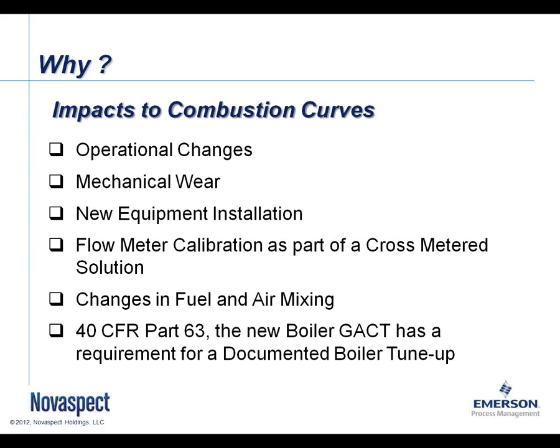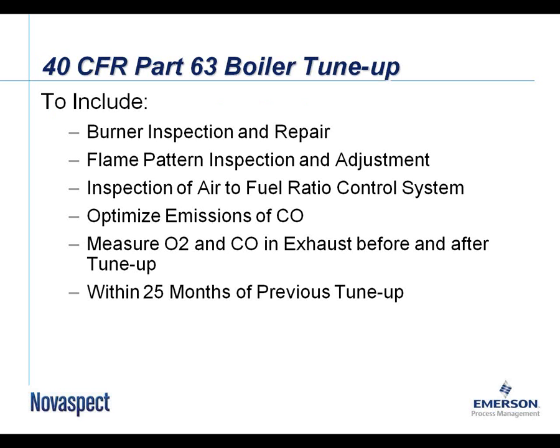And then also recently, as part of the 40 CFR Part 63, the new Boiler Act, there is a requirement to do tune-ups, specifically on oil, biomass, and some small coal burners. And that's actually subpart JJJJJJ, there's 6 J's in a row, for the subpart of the 40 CFR Part 63 if you want to look that up. But it requires a burner inspection and repair, flame pattern adjustment, inspection of the air-to-fuel control ratio system, which is the fuel air curves that we're talking about, ultimately optimizing the CO. So as you can see, there's lots of reasons to do this.